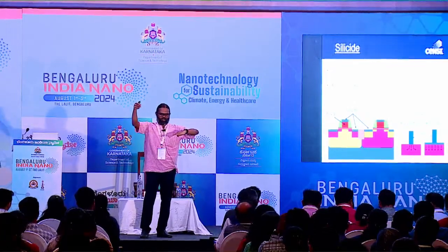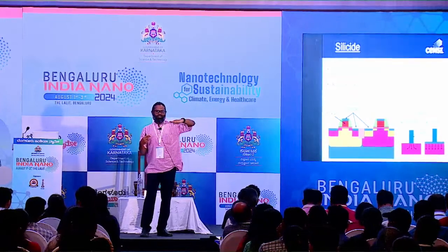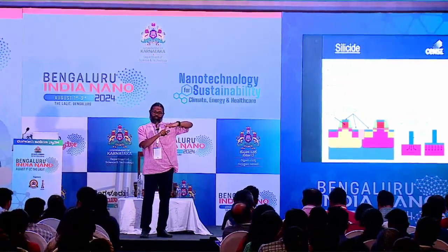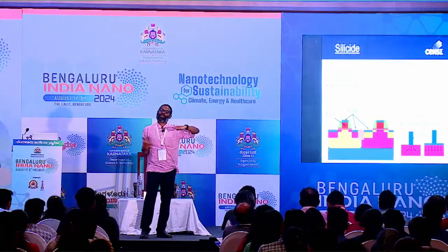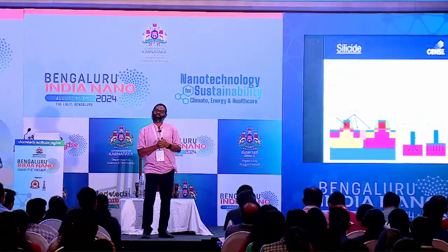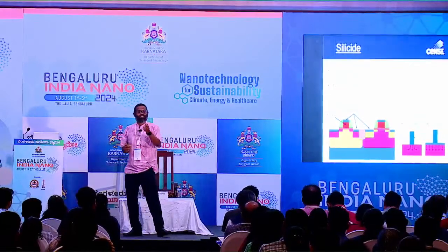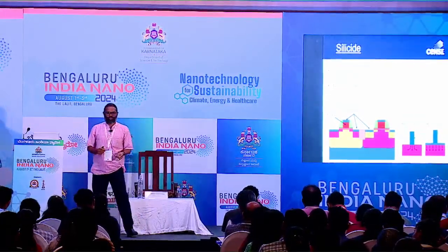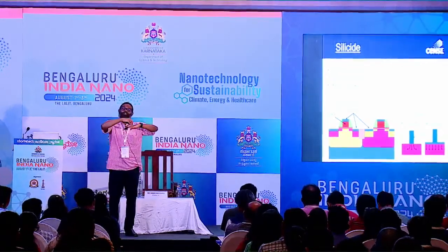I need to connect with the wire, right? I can do that. But the only trouble is, the conductor that I have is a semiconductor, and the conductor that I want to connect with is a metal. So it becomes a metal to semiconductor contact, which is not very trivial. That means the resistance for flow of electrons will be high if I don't take care of this junction.